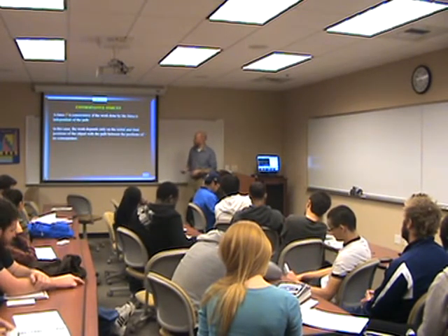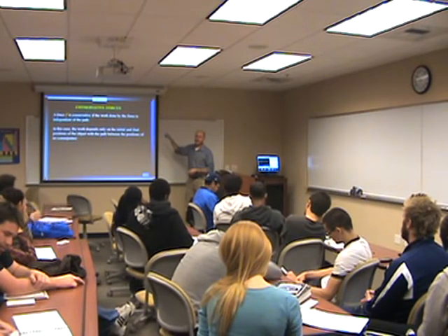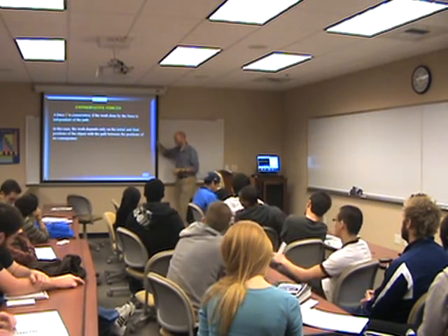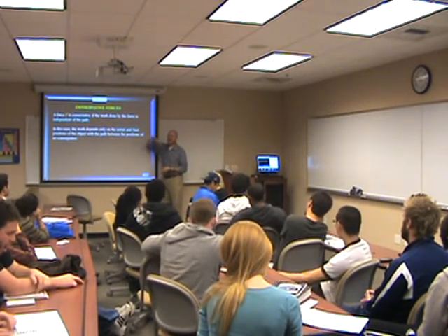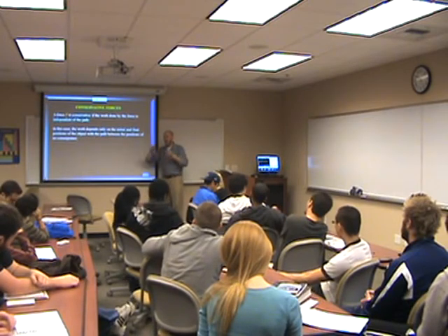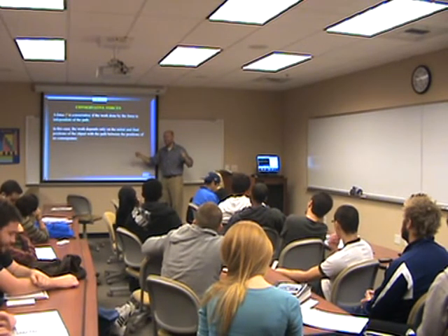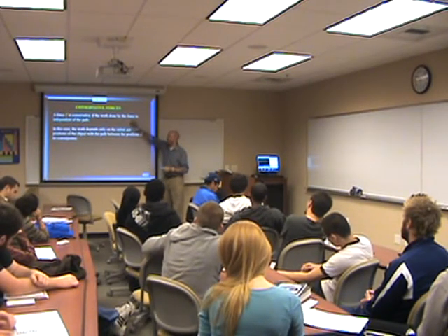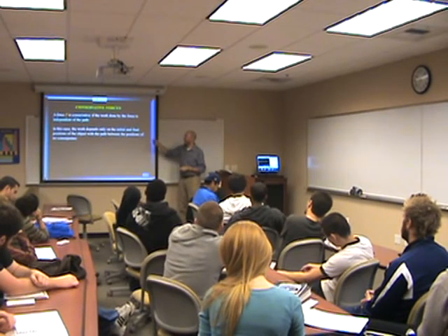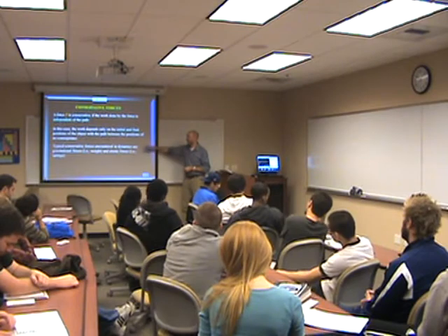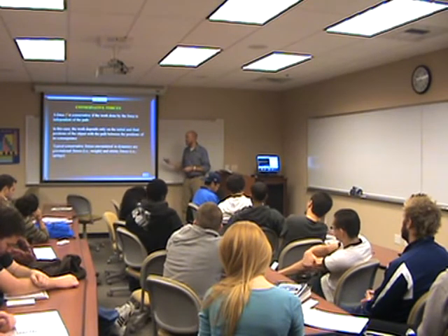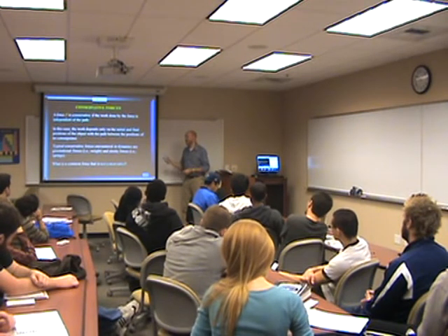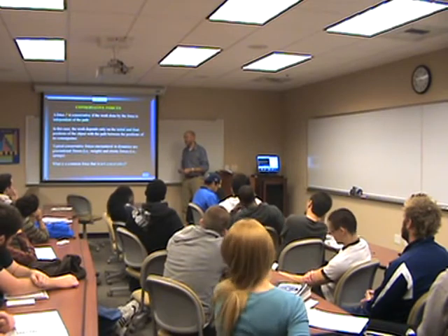So work is a conservative force. What's conservative? In dynamics, a conservative force is independent of path. Doesn't matter how you stretch your spring. If your spring has a certain stretch, it has a certain work to get it to stretch that far. Conservative force is independent of path, only on the initial and final positions. So gravity and elastic forces like springs are our true conservative forces. What's not conservative? Friction.